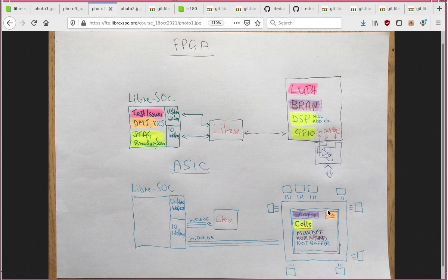But in this particular case, because it was defined externally by a LIP6 team, and because Yosys doesn't understand it, we actually had to mark that PLL cell as a black box to Yosys to get it to not try and do some optimization, etc. And likewise for the 4K SRAMs, of which we put 4 down. So you won't see a 4K SRAM in the FPGA, and you won't see a LibreSOC PLL in the FPGA, because we are using the existing PLL and the existing block RAM of the FPGA resources. Okay.